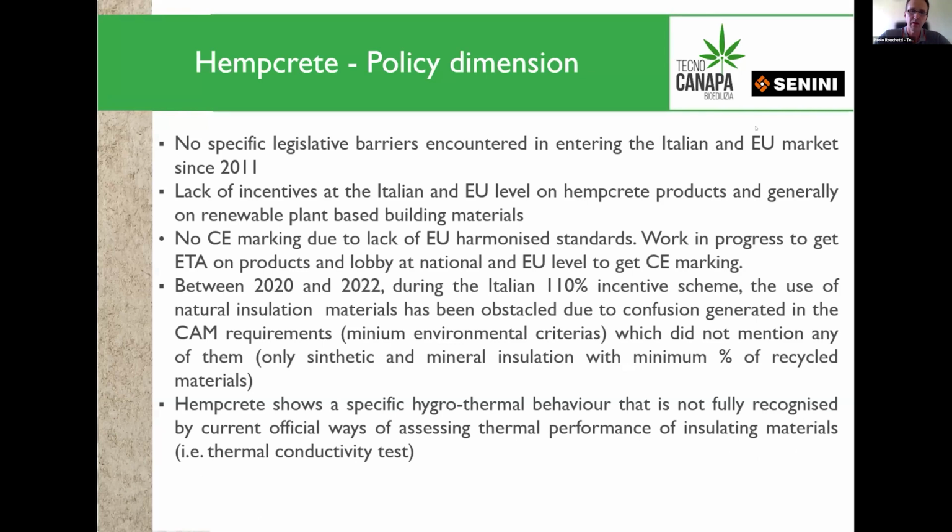Another issue that we are encountering in terms of policy is that hempcrete shows a specific hygrothermal behavior that is not fully recognized by the official ways of assessing thermal performance for insulating materials. Just to make it simple, the way to compare insulating materials is the thermal conductivity test, which is a test made for mineral or synthetic materials that are non-dynamic, totally stable.